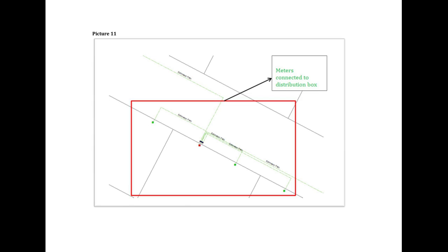Underground service connection from mini-pillar to meter: since the meter box has the same mini-pillar number but there is no route available from as-built, it is connected from the nearest mini-pillar with the same number as mentioned in the meter box.